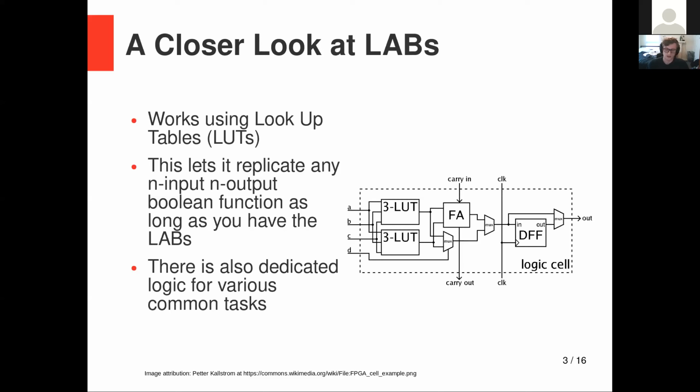I actually saw a class project, because Cornell teaches a class on these, and a class project they did was they actually made a hardware accelerated Mandelbrot fractal zoom. So some of you may have seen a Mandelbrot fractal zoom, zooming in on an infinitely complex thing, all kinds of pretty colors and stuff. But by building the circuitry purpose-built, they were able to do it much faster than a CPU, even though this thing has a much lower clock speed compared to a modern CPU, less advanced in a way. So you can get a lot by having dedicated circuitry for a task.